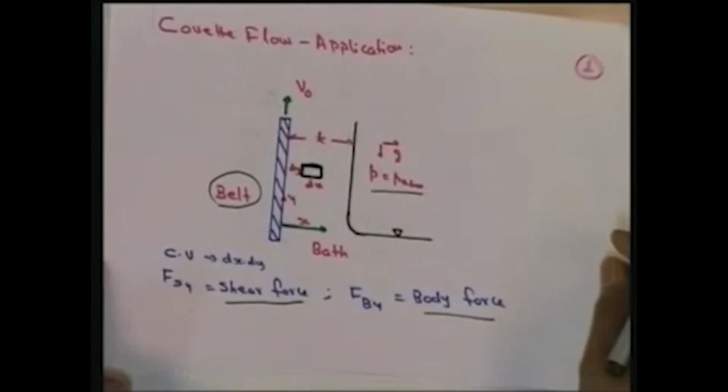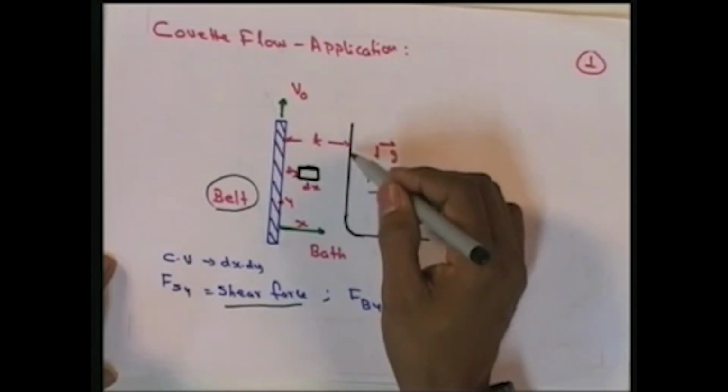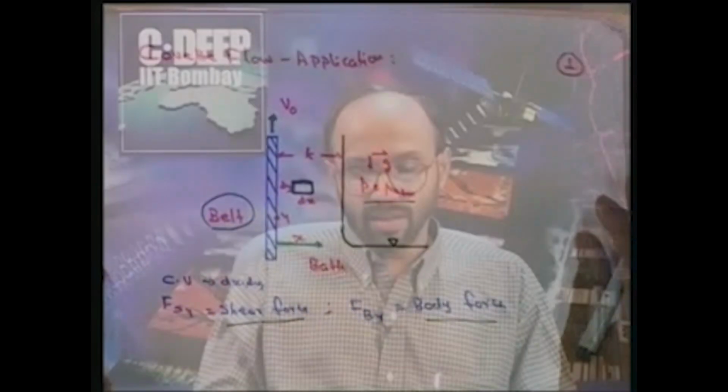Then also, since it is given as per the assumptions, at x equal to t, that means on the top of the fluid element which will be carrying the fluid, there will be no shear stress, so we can write tau is equal to 0. So, dv by dx is equal to 0.